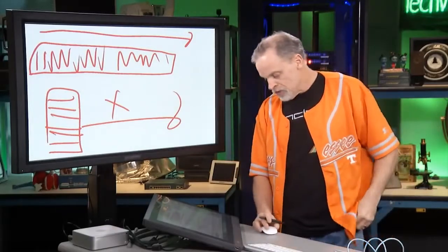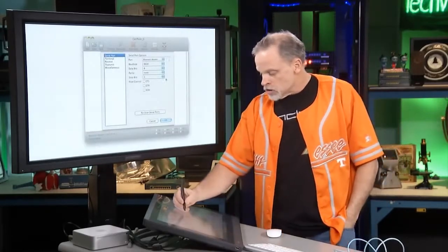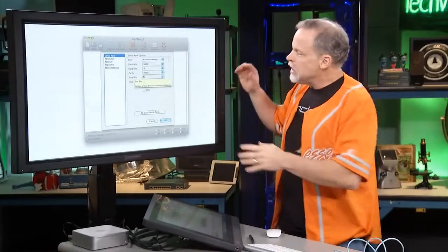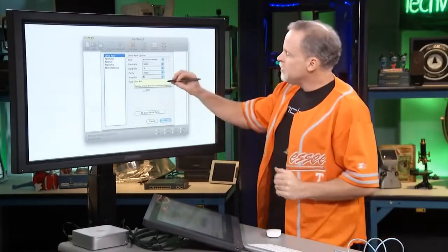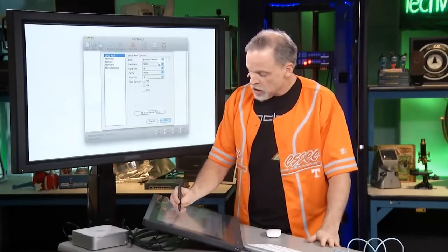Well, that's where this really cool stop bit feature comes in. Go ahead and bring that back up. Stop bits are actually telling your system where these frames end. And why that's important is because even though your devices agree that 9600 is what my speed is, every device is going to have its own little drift, right?